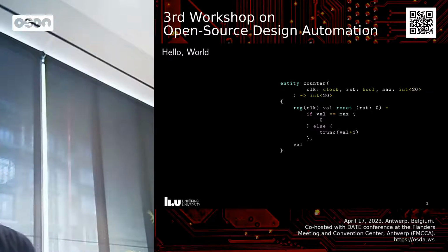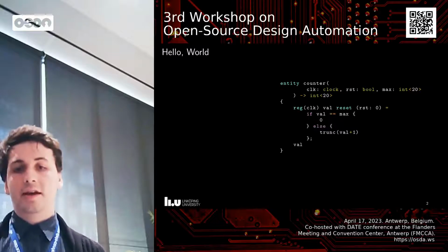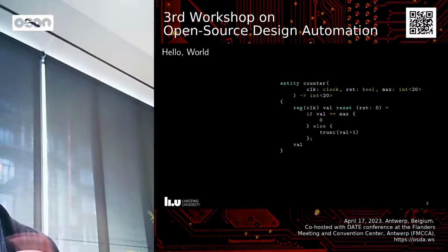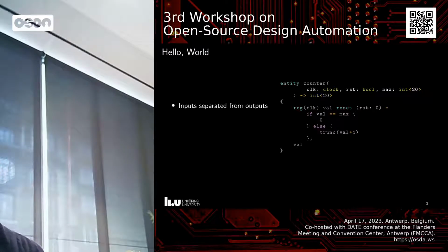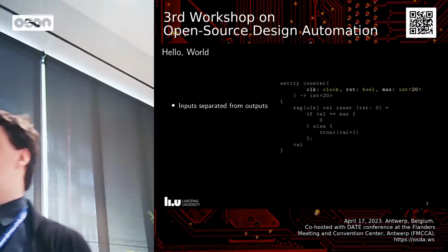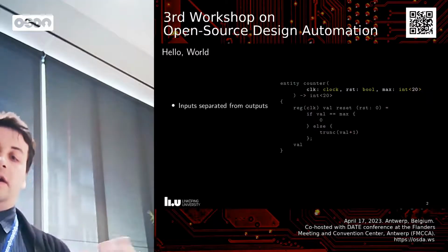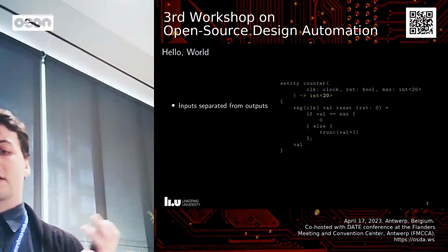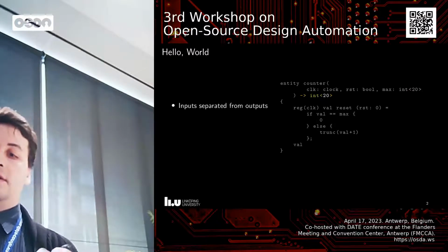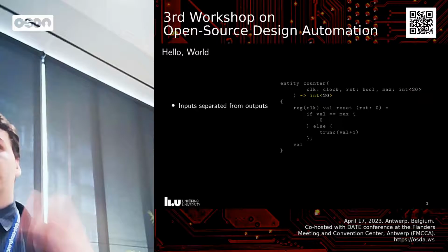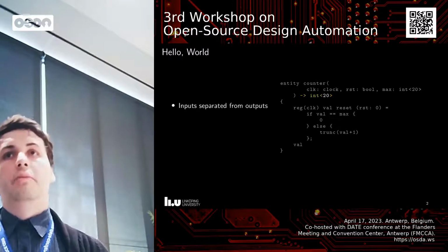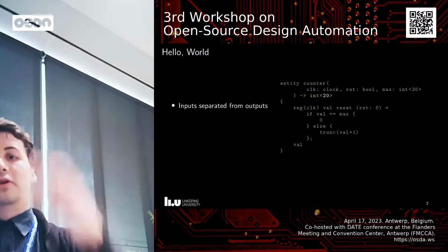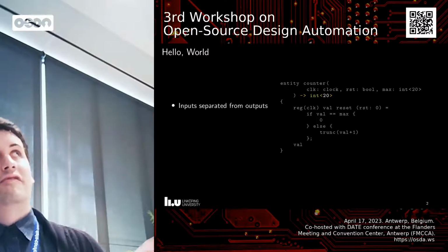So I want to start off with an example of what the language looks like. This is sort of the hello world, a counter that counts from 0 up to some maximum value. The inputs are separated from the outputs. So here we take a clock, reset and a max value, and this thing produces a current counter value. And the whole language is more linear than Verilog and VHDL, for better or for worse. But I think it's easier to reason about things in a linear way and then explicitly do non-linear flow of data, I suppose.